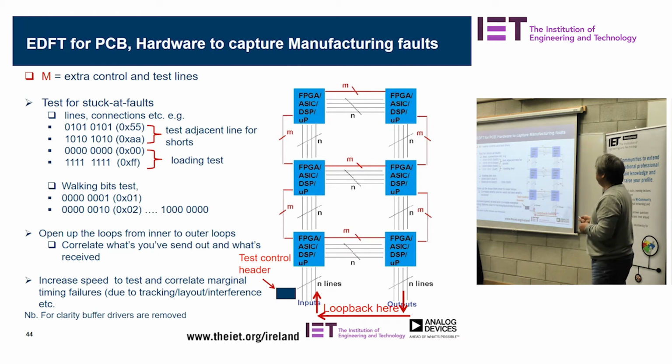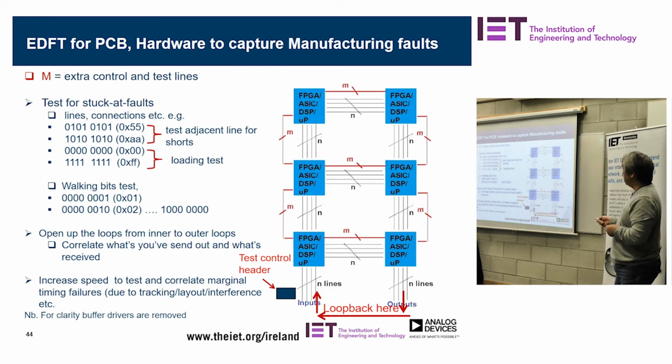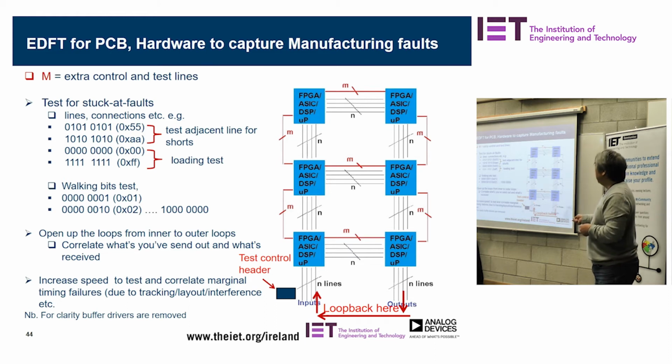What we do is have a system diagnostic test. You have those loopbacks here. So this FPGA will talk to this one, with the tracks running across. When this one sends the information here, and this loops it back, and we receive the same information back, that means the manufacturability is good, so the track is not shorted.